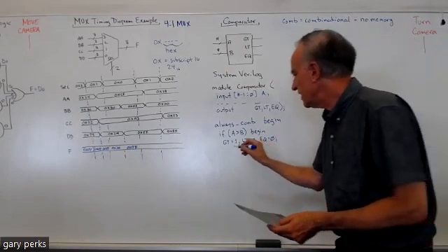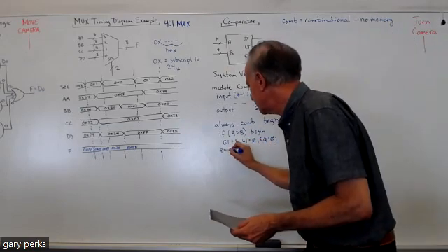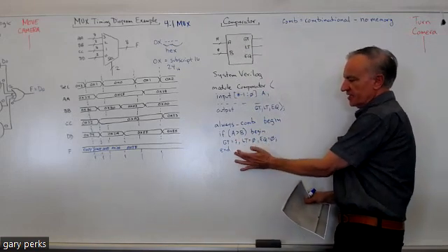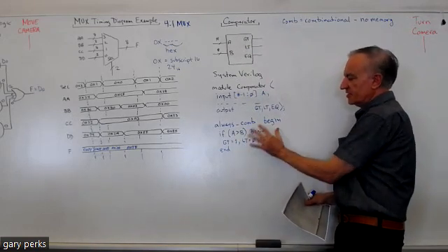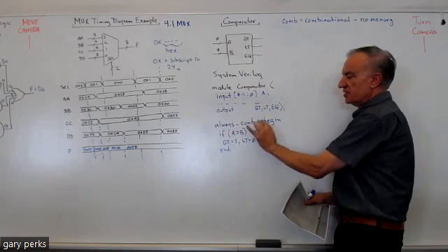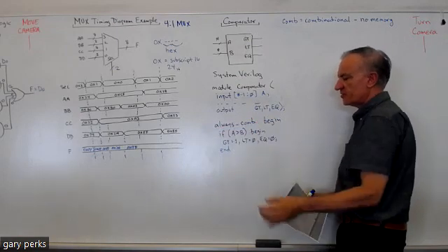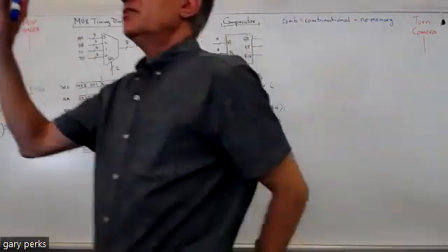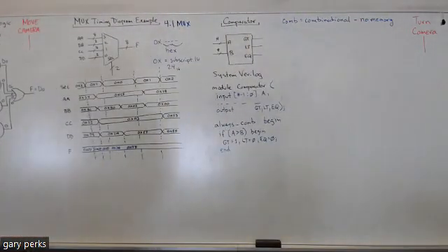And then we have to put an end that goes with this begin. So this end and this begin go together. This begin is for the always block, and the end for that is going to be later on. So your if statement can have either 0 else ifs, or it can have as many else ifs as you want.